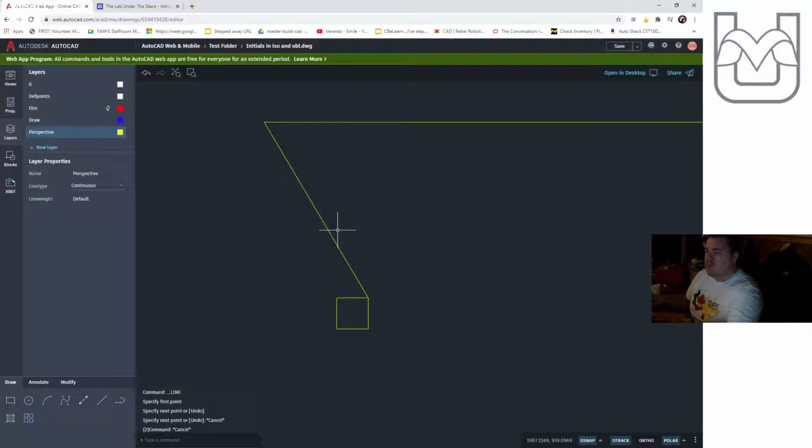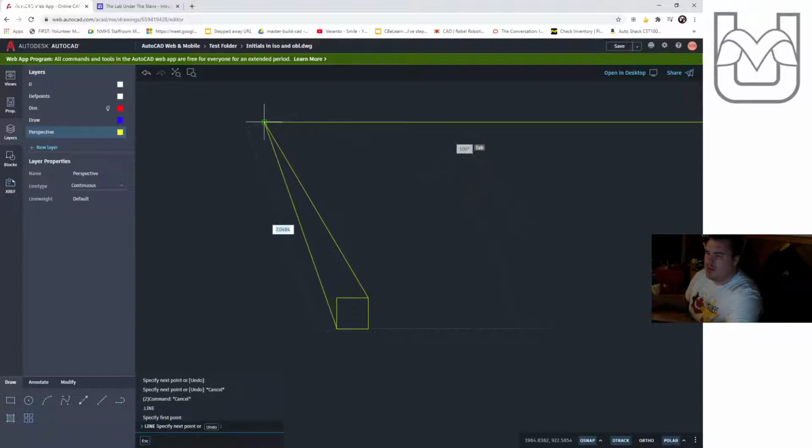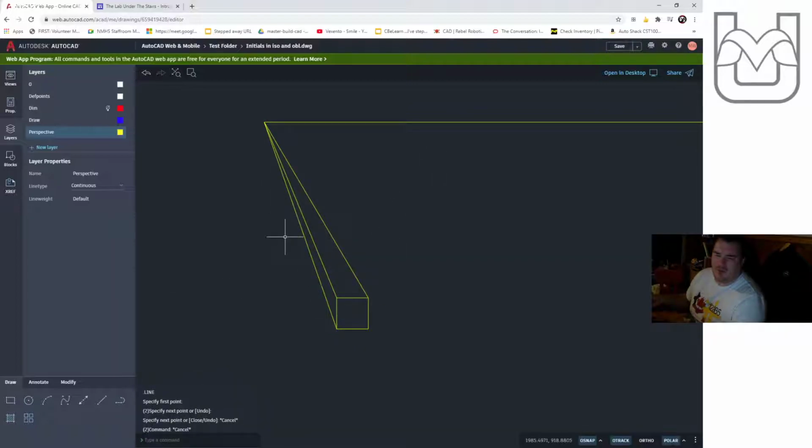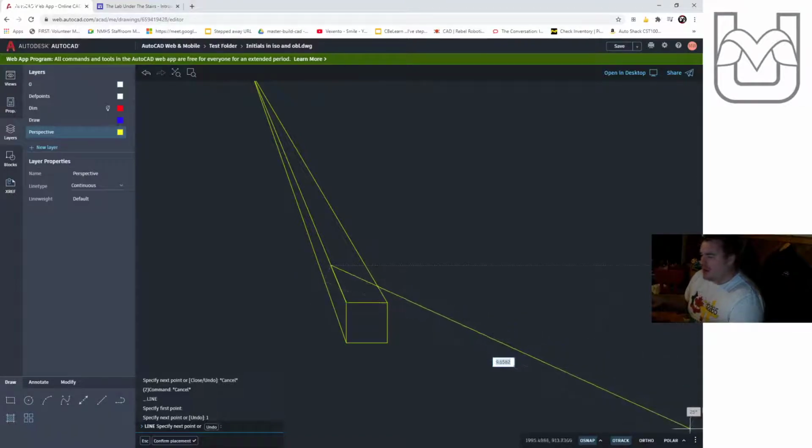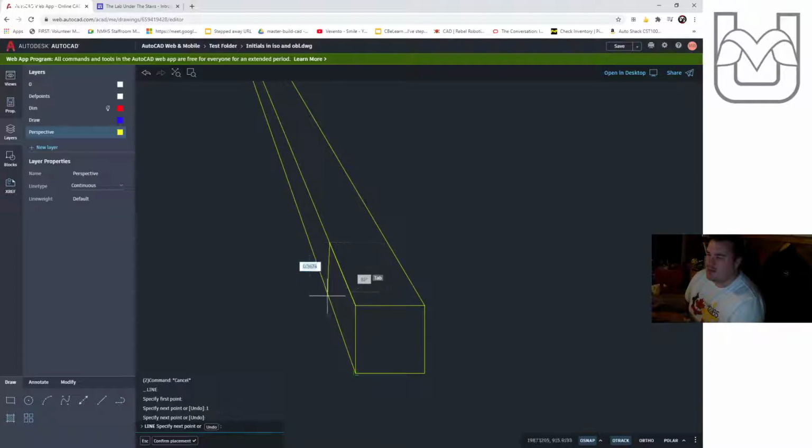And you'll notice that my polar snaps are still on. I can leave them on. I don't have to turn them off, but they might be annoying to some people because sometimes they get in the way when you're doing things. So if you want to turn those off, just click polar down here, and life is good. What I'm going to do now is I'm just going to simply draw another line here, and we draw it up from the nearest corner to me. And I'm going to make this one actually accurate at 1 unit across. And then I'm going to realize I turned my polar snaps off. I'm going to turn my 90 polar snaps back on because I kind of need them. And let's see what we can do. This line obviously doesn't have them applied, so let's find the end of the line.